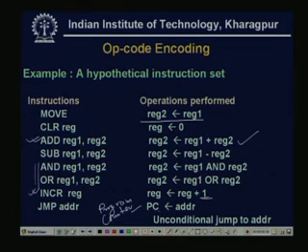The address where I want to jump, I give that value to the program counter, and we know that the program counter always contains the current address. So, it will jump to that particular address. So, these are the meanings of these instructions. If we give these instructions, the operations to be performed are specified by the right hand side expressions.